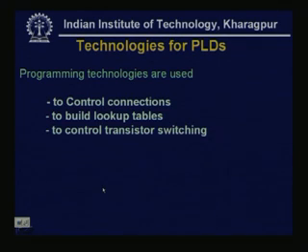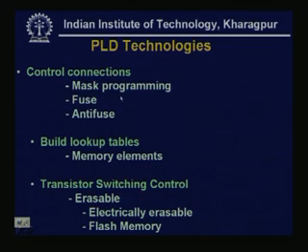Now, what are the technologies for PLDs? Technologies means mainly the programming technologies. Programming technologies are used to control connections, to build lookup tables and to control transistor switching. Now, one by one we see that. First we see the control connections. These normally use mask programming or fuse and anti-fuse.